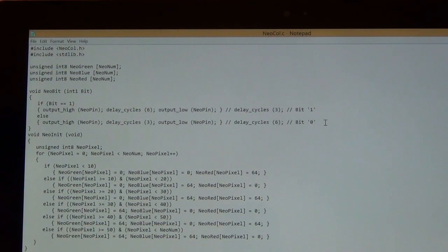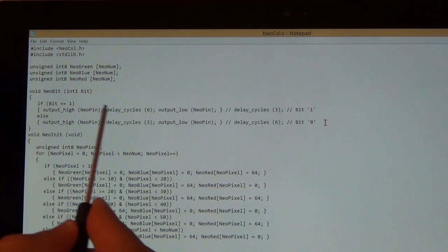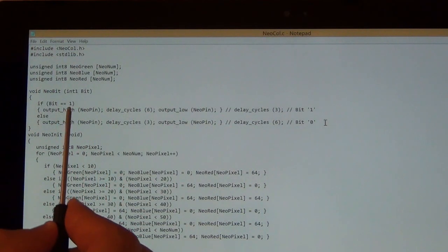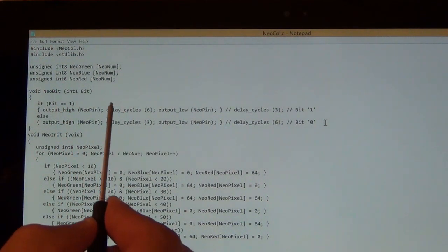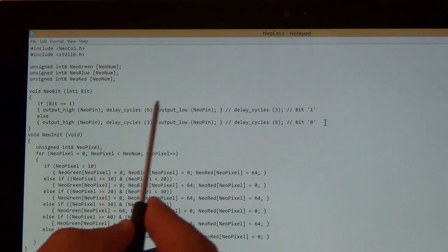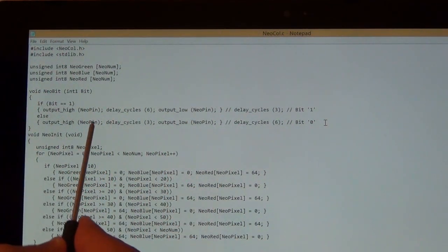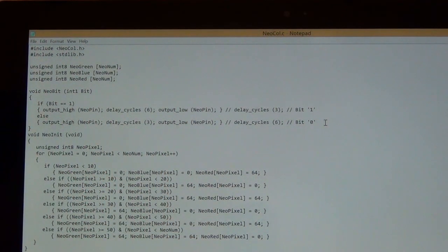And that's where the trick is. The compiler will have to expand this out into a whole bunch of assembly or machine code statements that actually take time, and you have to take that into account. Going from this command to this command is immediately followed, so from here to here is just the next instruction. But from the last command back to the beginning is not. There are many other commands that have to be taken care of by the CPU, which take time, and we will see that.